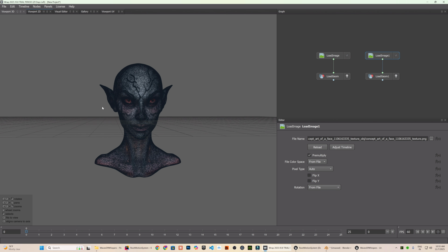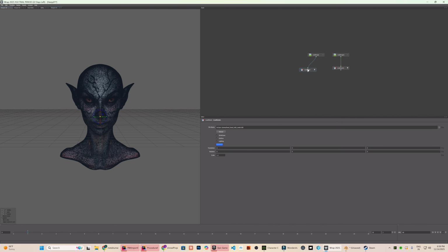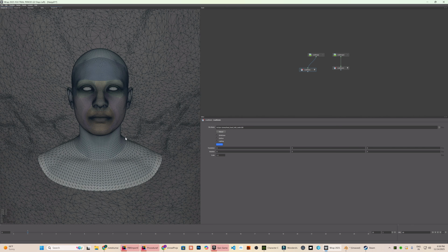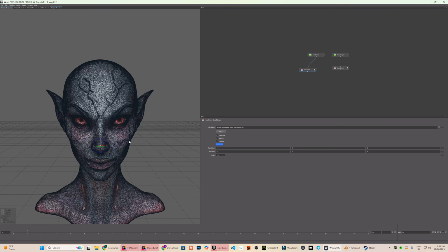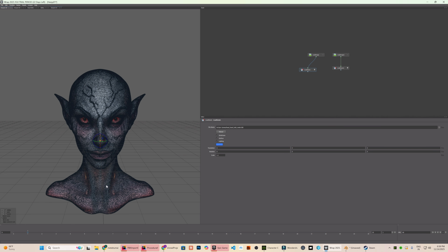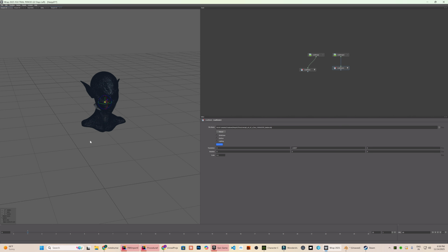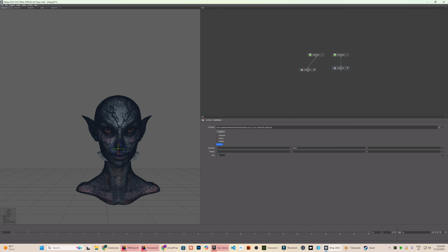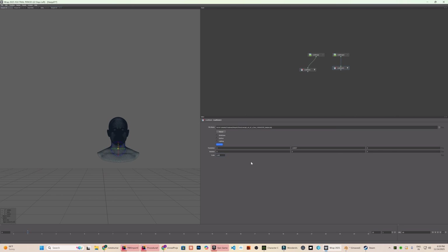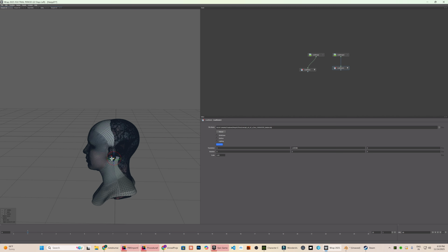You can see that I am working in the viewport 3D tab here, where I can view the geometries in a proper perspective view. When I click on either of the loadgem nodes and press F, the viewport focuses on that particular character. At this stage, I actually need to align the two meshes because that makes the next steps much easier to handle. You can see that I can adjust the translation, rotation and scale to roughly align the target geometry with the source one. It does not need to be an exact match, and approximate alignment is perfectly fine.